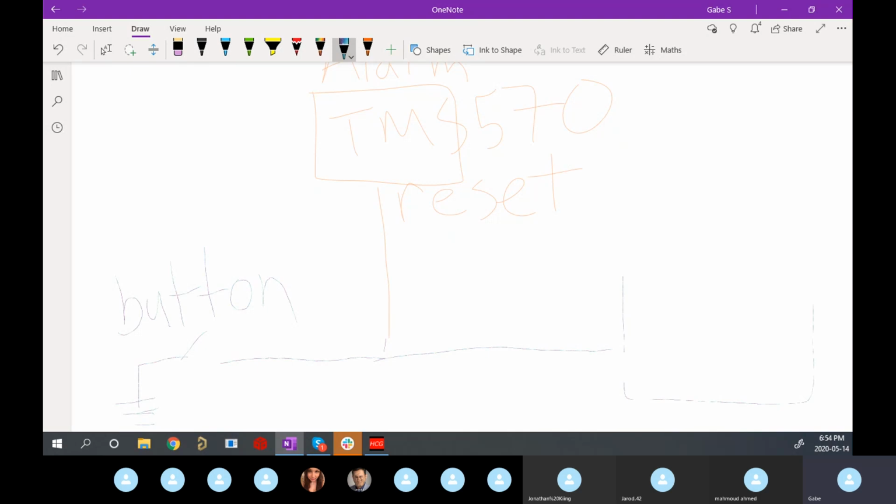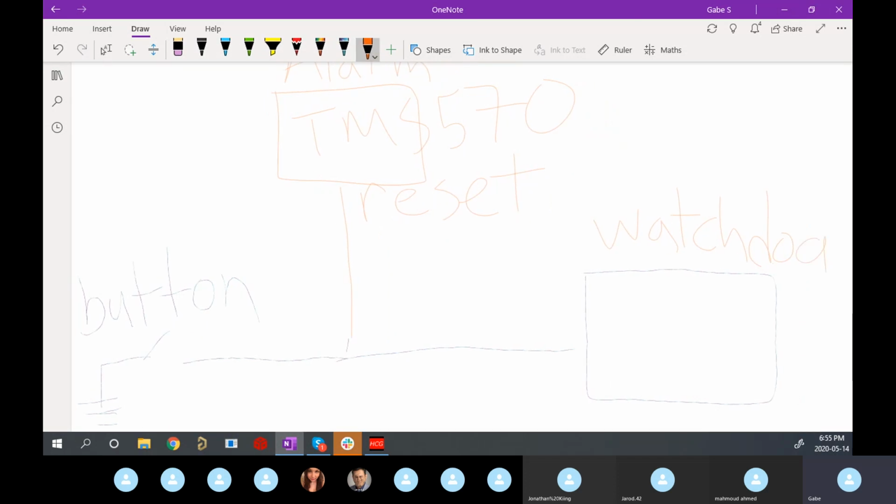And the other thing is a little guy called a watchdog. We'll talk about this in another lesson, but you can essentially think of it as a little pet that's helping you out. This little pet is checking around the system, looking everywhere, and if something goes wrong, he's going to send a 0 to this line. Otherwise, he's open drain. So these two things can work in tandem. Pull up resistor, of course, to make sure that if they need to, they can reset the TMS 570, but they're never going to cause a short, and they're never going to break the system while trying to save it.